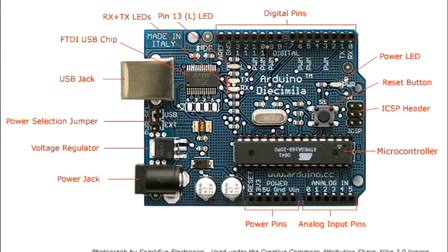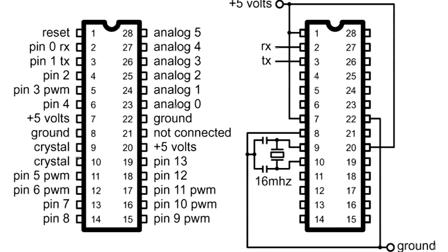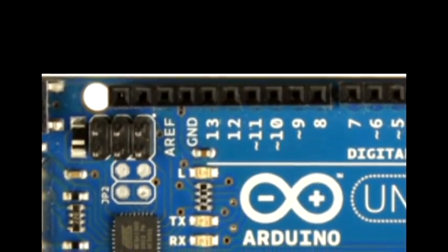I'll talk a little bit about the microcontroller. The first section discussed in the microcontroller section is the digital pins. The pins are configured as either inputs or outputs. An important piece of info that we first want to consider is that the vast majority of Arduino analog pins may be configured and used in exactly the same manner as digital pins. Arduino pins default to inputs, so they have no need to be explicitly declared as inputs with pinMode. Pins configured as inputs are said to be in a high impedance state.